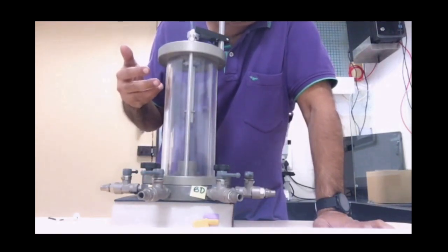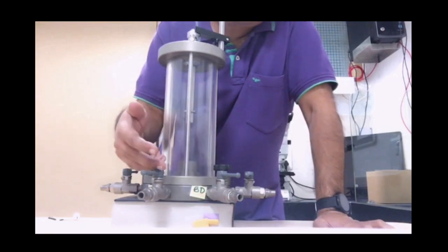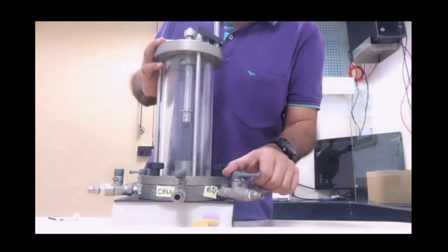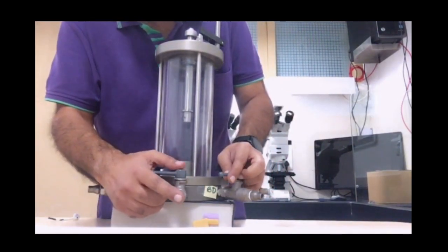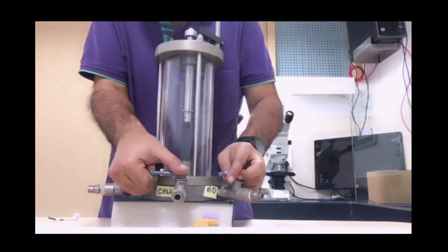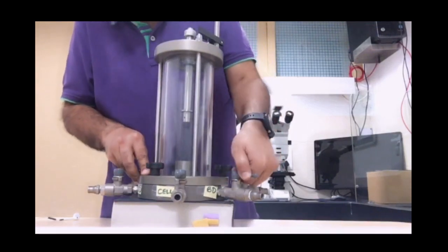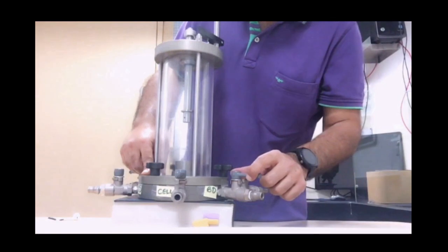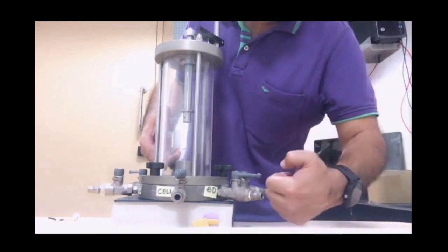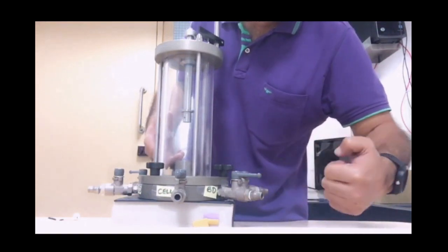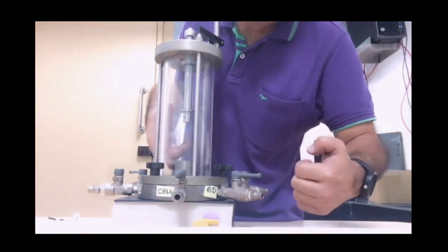It can take about a day, and for some impermeable soils even more than a day, for the whole thing to stabilize. To give an example, the cell pressure I have increased from 50 to 200 kPa. That's 200 over here. Now 200 is within the chamber, and the back pressure I have increased to 190. So the pore pressure within the sample was 40 kPa, but now this 190 goes and hits the sample, bombards the sample. So the pore pressure within the sample is going to increase and reach a value of 190.